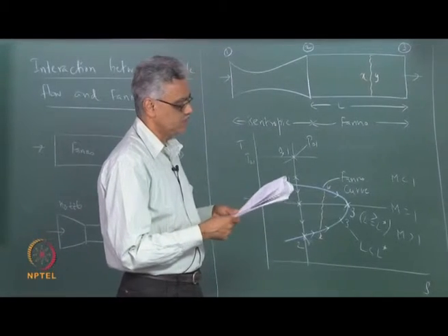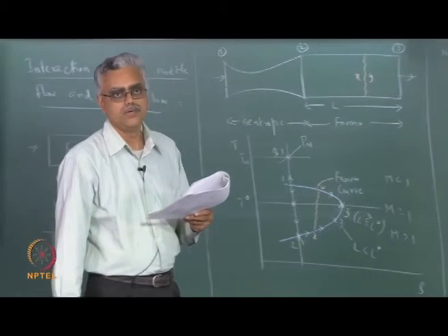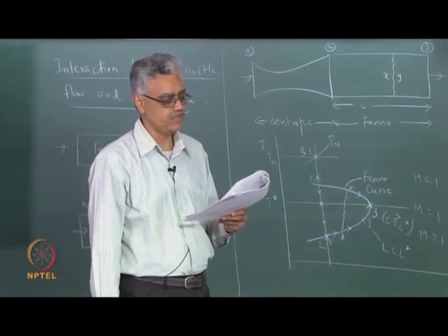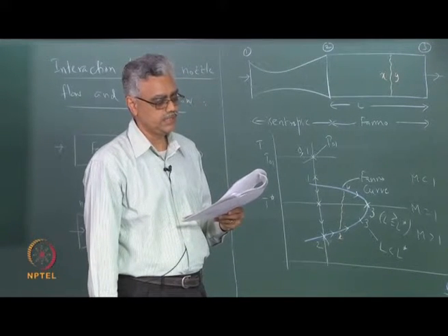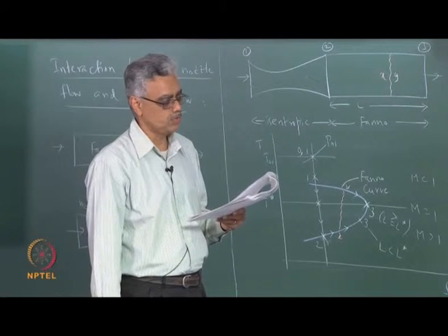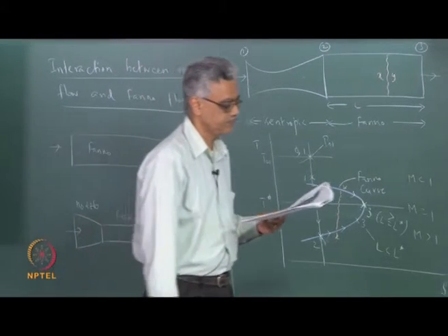The stagnation conditions at the nozzle inlet are 1 megapascal and 500 Kelvin. The pipe diameter is 0.05 meters and it is 5 meter long. Determine the reduction in mass flow rate due to the presence of the pipe. Take f to be 0.024 and the back pressure to be 100 kilopascal.